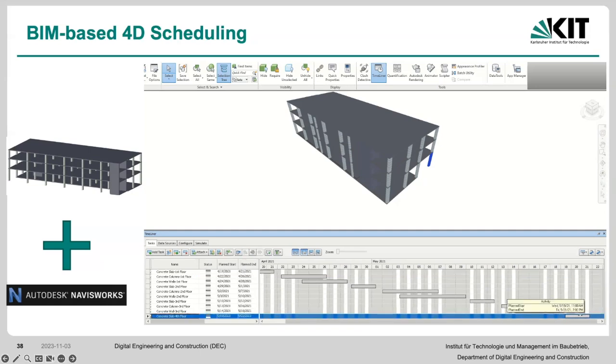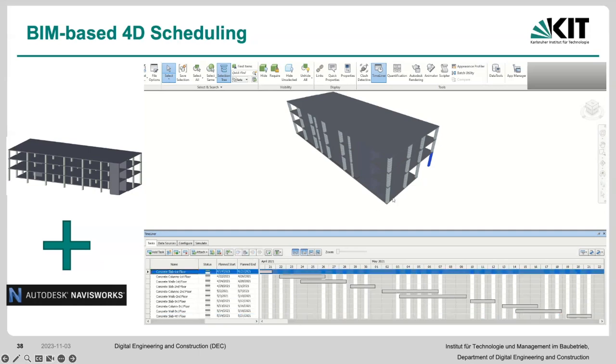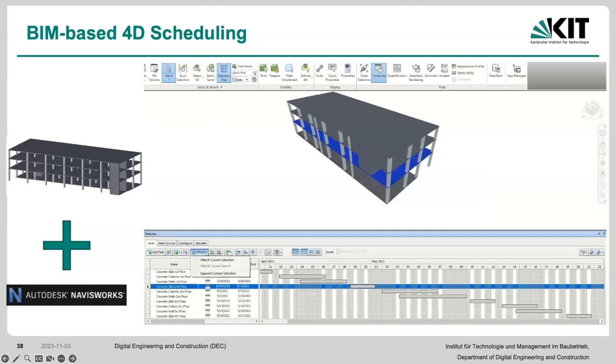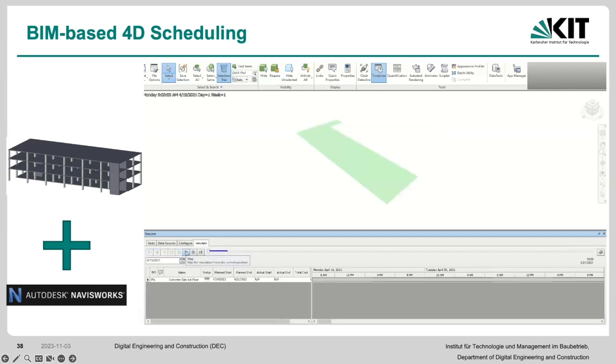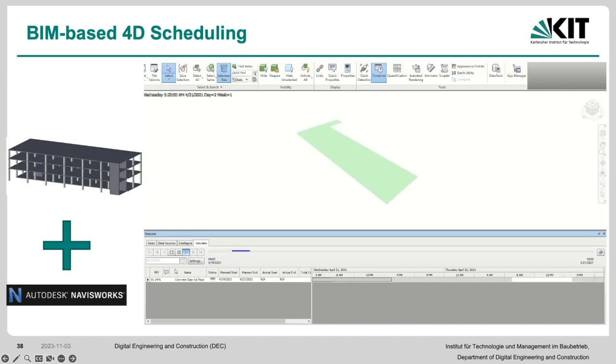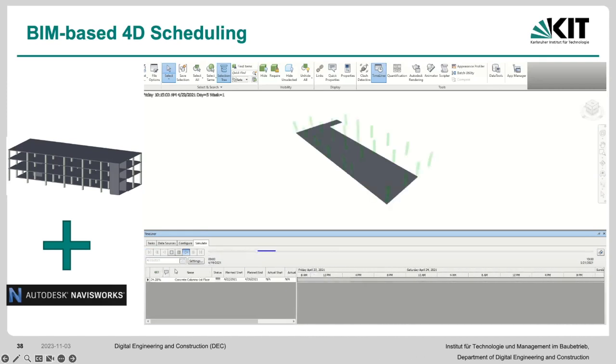Using that, you would be able to simulate it. And once you have that simulation, you can know more or less how this structure is going to go, and then you can have it in much more detail. If you, let's say, have temporary facilities here as well, temporary elements, you can have shoring there, you can have the formwork. It depends on the type of building that you have. You can model each and every one of these parts, right? And once you model it, that means that now you have a collaboration and agreement between whatever scheduling software and scheduling method you're utilizing, so the project management side of it, and whatever geometry is going to be built in terms of your production activities.